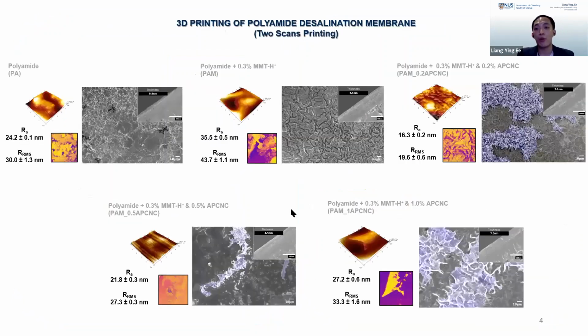So an additive approach is presented that uses electrospray printing to deposit monomers directly onto the UF substrate, where they react to form a polyamide layer. Using high voltage, the two precursors are sprayed onto the substrate and polymerized on contact. This small droplet size coupled with the low monomer concentrations that we optimized results in polyamide films that are smoother